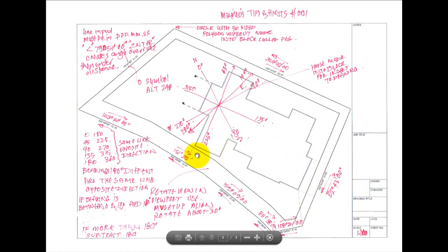I noticed that they had a further dimension over here, which can really only be a check dimension, because you'll get different little errors in these boundaries that are not really definable in AutoCAD, and it can be quite significant. In terms of this set out, there's one nice good fixed position there. This position here is floating, in other words it's lining up along that wall, so it's not in any fixed position. And then we can see what happens over here, and as it turns out, I think I was a millimeter out for that line.